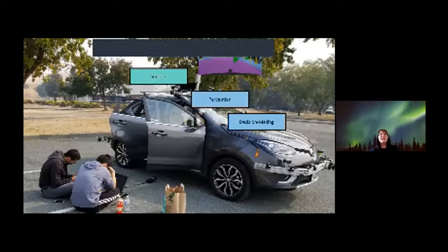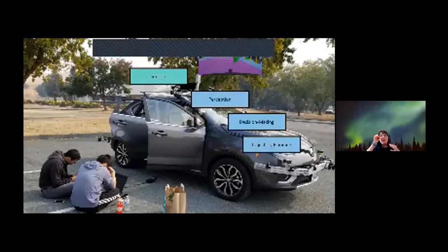So these decisions can be high-level abstractions. Like in the case of an autonomous vehicle, this can be a decision of whether or not to stay in our lane or make a lane change. Or this can be something a little bit lower level, like a command, like a set speed for a cruise control. But regardless, this is going to be some sort of reasoning or some sort of abstract decision. And this gets passed down to our trajectory or motion planning module.